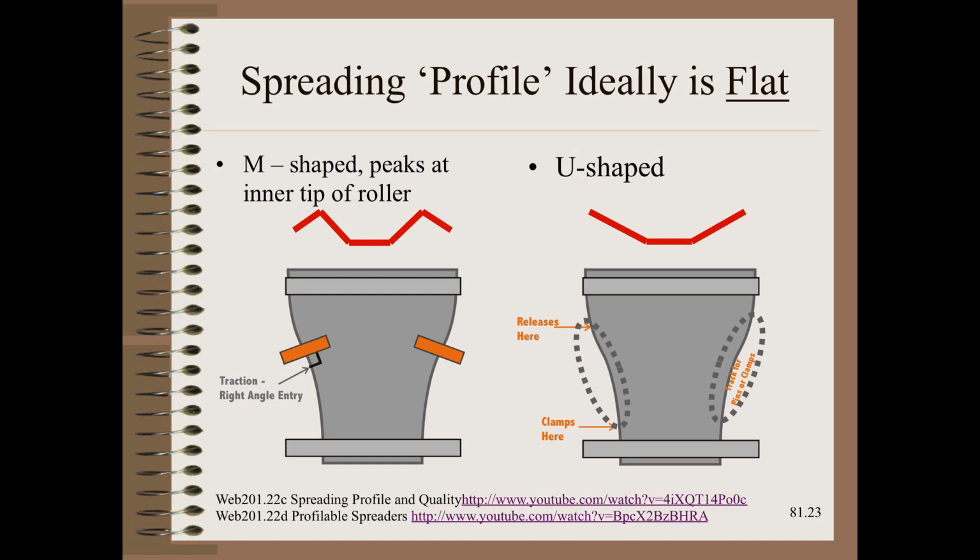Most of the spreaders we discussed earlier, when well designed and well applied, will apply an equal cross-direction spreading force at all points across the web. The spreading profile is then flat. Obviously, all bets are off, however, if we overbow a bowed roller as one example.